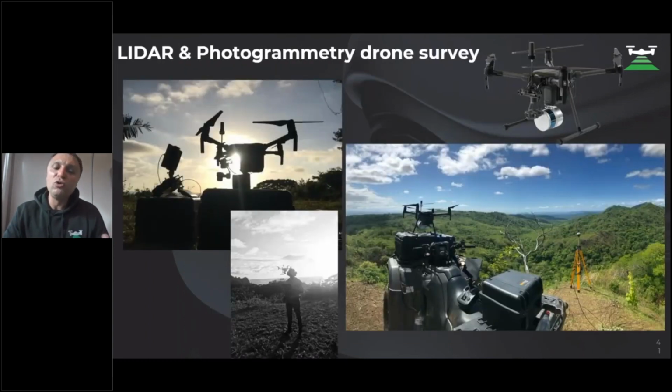And this is why we would suggest to use photogrammetry together with the LiDAR system. And I would like to show you data processing of the LiDAR on the project which was made by our customer from Costa Rica. He used Matrice 200 with the LiDAR and X4S camera. And X4S camera is connected to the LiDAR as well to synchronize it and to capture coordinates of each image.